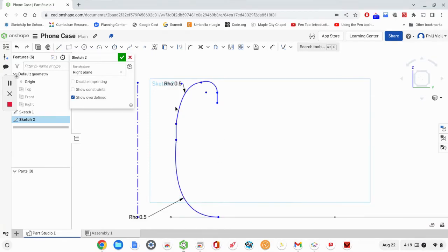All right, so the general shape, you can see it's just still quite a bit wonky. So we're going to add some constraints here to let it be nice and smooth as the transition goes through the different line segments here. So the first thing we want to do is a vertical relationship between this point and the radius point.